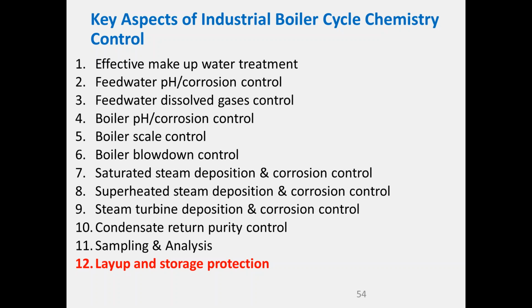And the boiler itself, obviously, if you've got automatic blowdown control, there'll be a conductivity or a TDS controller in there. I would recommend pH on the boiler as well. But for pH, you've got to have a sample point which has a sample cooler to bring the temperature down.